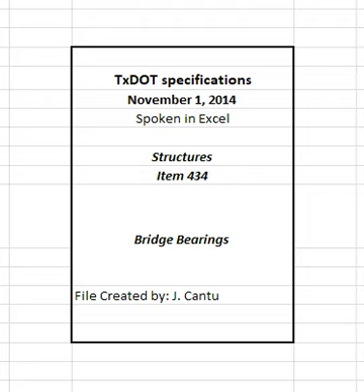Mold together components of a laminated bearing to form an integral unit free of voids or separations in the elastomer or between the elastomer and the steel laminates or plates, unless otherwise shown on the plans. Provide well vulcanized elastomer between the laminates or plates and on the outer surfaces of the bearing that is uniform and integral and resists separation by mechanical means into separate, definite, well-defined elastomeric layers. Evidence of this layered construction, either at the outer surfaces or within the bearing, will be cause for rejection. Repair of damaged elastomer on sides of laminated bearings is not allowed for product acceptance.